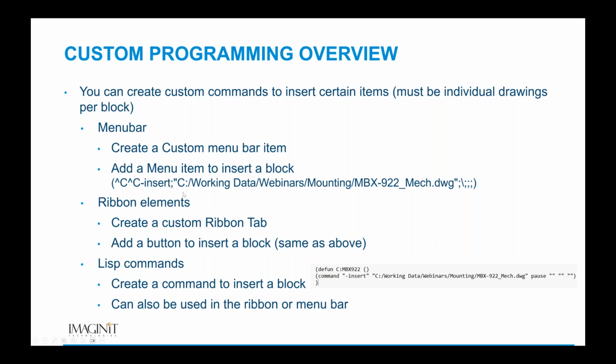Is there any training available on AutoCAD VBA? We don't do any. I'm probably one of the few guys left here that actually knows VBA well enough that I can help fix a lot of that stuff, but we generally don't deal a lot with VBA anymore. The only reason is that Autodesk has been saying for years that they might eventually no longer support it. They haven't pulled the trigger on that yet, so I either want to keep it in Lisp, which will always be part of AutoCAD, or I want to move that to a .NET environment with a DLL. That would be my recommendation. VBA works really well. The problem is we don't know how much longer it's going to be supported and included. So just heads up on that.